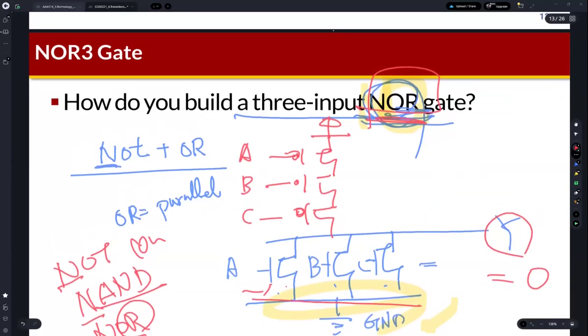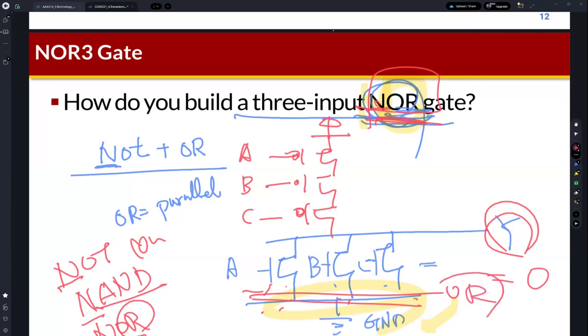So which means you can make this NOR using the NMOS transistors. So OR is mapped to the parallel connections of NMOS transistors. So which means that for the Y, we can make Y 0 using the parallel connections of NMOS transistors. Okay, parallel. So it's an OR, but because of the negation, this is NOR. And then the topology of the PMOS transistors is the inverse of the topology of the NMOS transistors. So which means this is serial. Okay, we can connect the PMOS transistors like this. So I hope you can understand this.